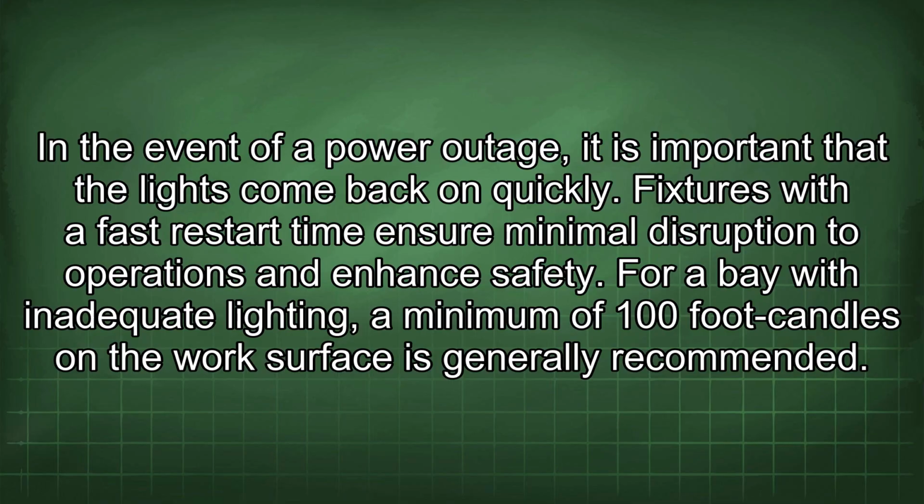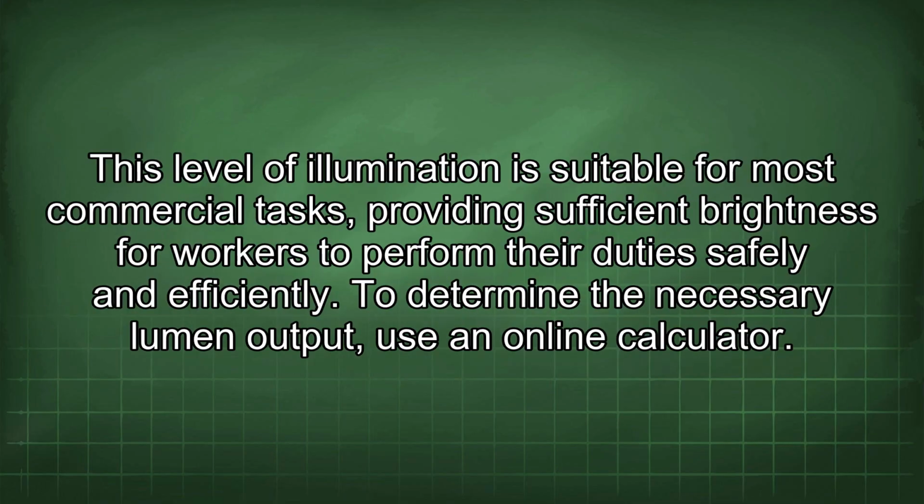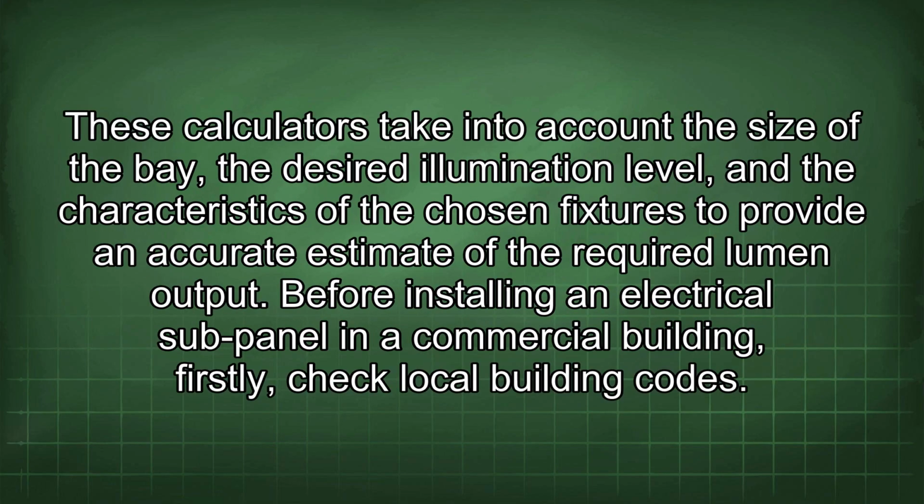For a bay with inadequate lighting, a minimum of 100-foot candles on the work surface is generally recommended. This level of illumination is suitable for most commercial tasks, providing sufficient brightness for workers to perform their duties safely and efficiently. To determine the necessary lumen output, use an online calculator. These calculators take into account the size of the bay, the desired illumination level, and the characteristics of the chosen fixtures to provide an accurate estimate of the required lumen output.